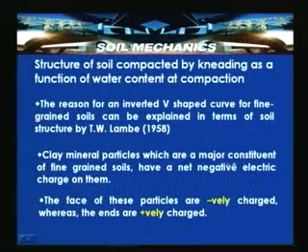As you all know, clay minerals are the major constituent of fine grained soils and have a net negative electric charge on them. The reasons were discussed in the previous lectures. The faces of these particles are negatively charged, whereas the ends are positively charged, because of the breakage of the bonds. So this causes attraction and repulsion depending upon the availability of water in the soil.